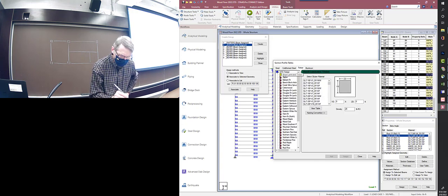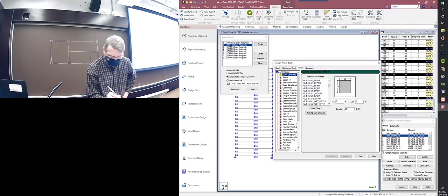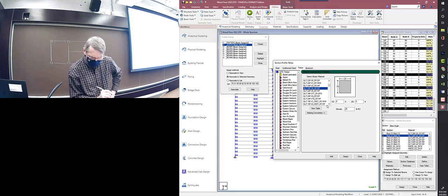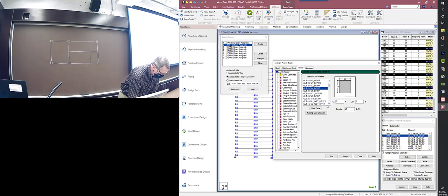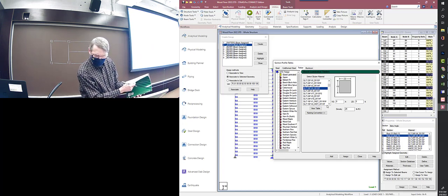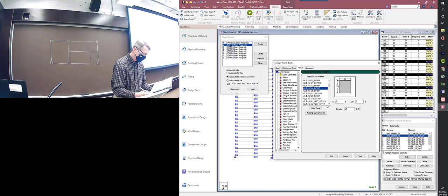This is going to be glulam, 24 FV4 Doug fir. Oh, good. Okay, that one, and then this is what I got to change. So it was 21, and here STAAD's no help. It doesn't tell you what size. You gotta pick it. So we already went 675. Let's just make it a little bit deeper. 675.